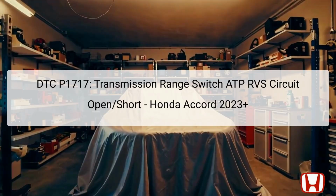The DTC P1717, specifically related to the transmission range switch, occurs when there is an open or short circuit in the ATP RVS, automatic transmission position reverse switch signal. This DTC is triggered when the TCM, transmission control module, detects that the ATP RVS signal is off when the shift lever is in the R, reverse position.